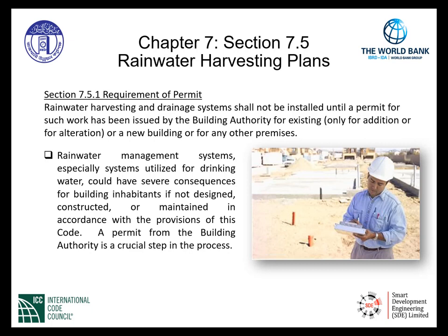The permit requirement will also give the applicant a requirement to submit construction documents for review and approval. Additionally, we're really concerned about the materials, the connection methods, and where we are getting the rainwater from and the treatment of rainwater before it is allowed to be reused for some purpose.